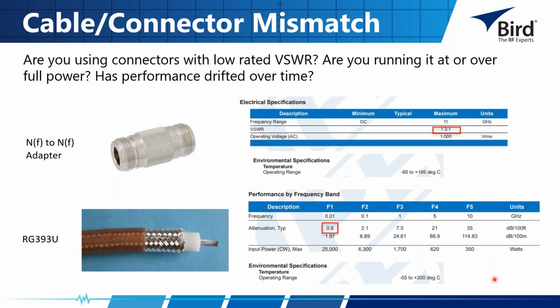So in terms of cable connector mismatch, any cable connector you're going to be putting into your system is going to have its characteristic impedance built by the idea of concentric circles. They're going to have a center conductor, and you'll have some dielectric medium, and then an outer conductor. All these pieces are coming together in such a way that you're forming this approximately 50 ohm impedance.